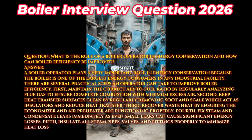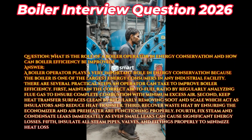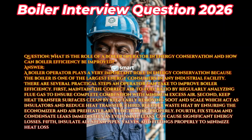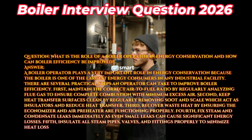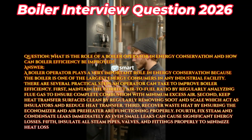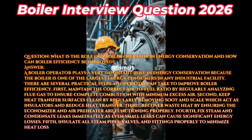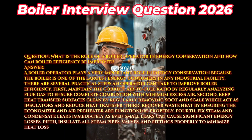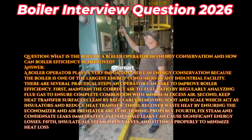Second, keep heat transfer surfaces clean by regularly removing soot and scale, which act as insulators and reduce heat transfer. Third, recover waste heat by ensuring the economizer and air preheater are functioning properly. Fourth, fix steam and condensate leaks immediately, as even small leaks can cause significant energy losses. Fifth, insulate all steam pipes, valves, and fittings properly to minimize heat loss.